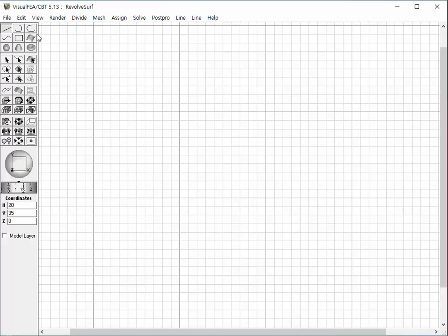The next example demonstrates mesh generation by revolving multiple number of curves. Press Elliptic Arc tool. Select Quarter option item from the pop-up menu if the current option is not set as quarter. Create a quarter elliptic arc. Press Straight Line tool and create 4 straight lines. The elliptic arc and 4 straight lines are forming a closed loop.